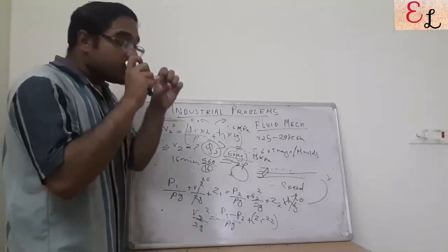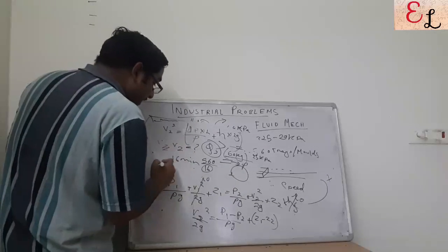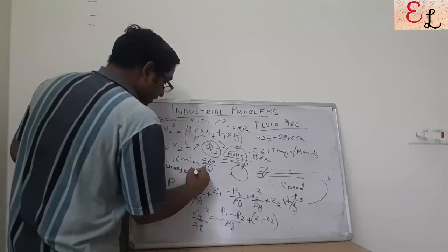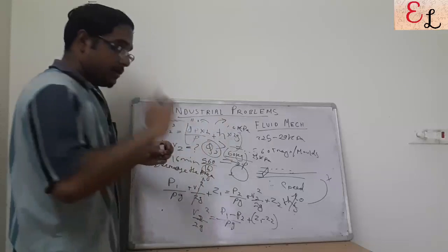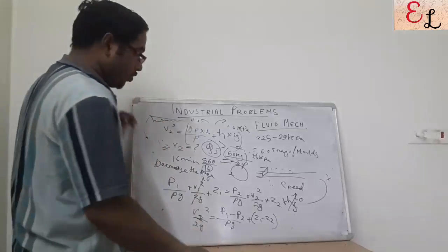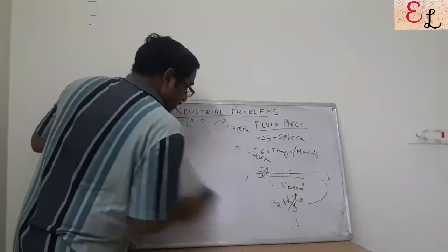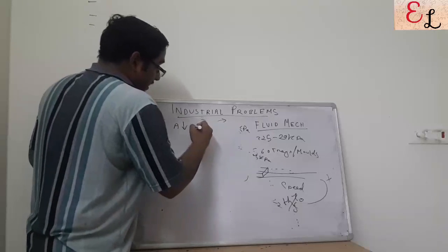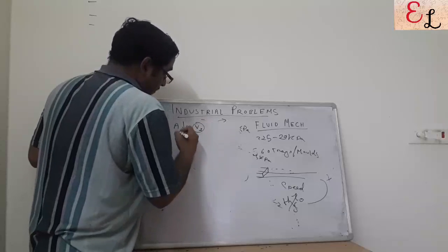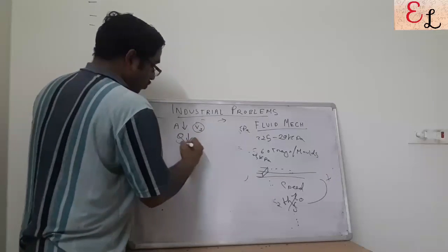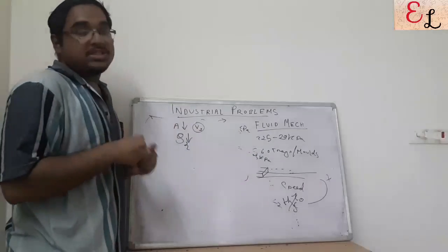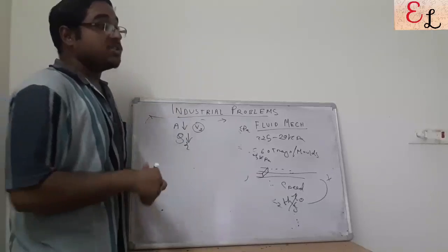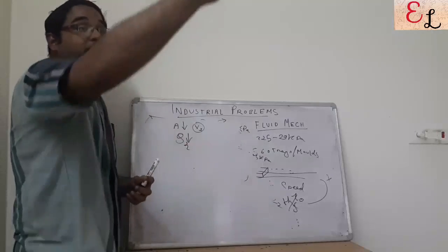So what we did is, first suggestion was decrease the diameter, the area, the outlet area. So the hole size we told to decrease. Our first suggestion would be to decrease the hole size. Once the hole size decreases, V2 is same, the Q2 decreases. Because we know Q2 is nothing but V2 into A, area of the hole.